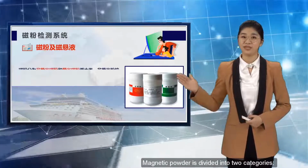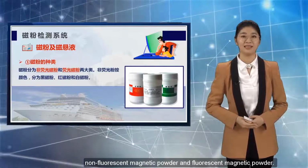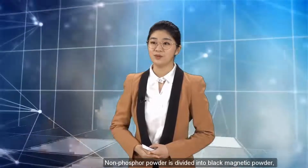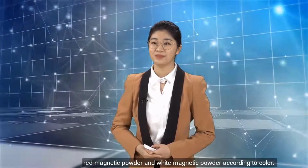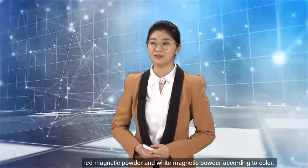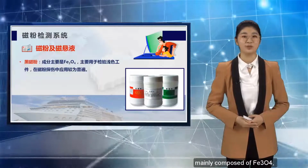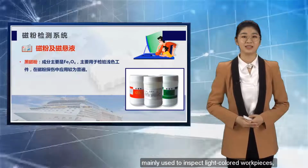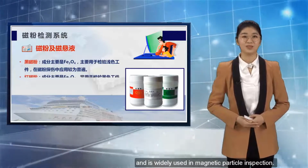Magnetic powder is divided into two categories: non-fluorescent magnetic powder and fluorescent magnetic powder. Non-fluorescent powder is divided into black magnetic powder, red magnetic powder and white magnetic powder according to color. Black magnetic powder, mainly composed of Fe3O4, is mainly used to inspect light-colored workpieces, and is widely used in magnetic particle inspection.